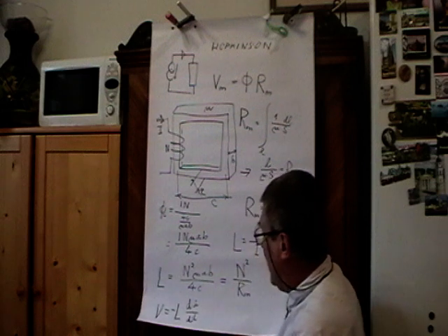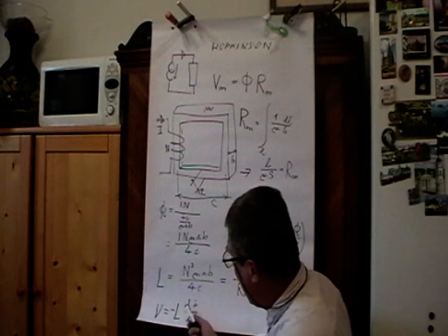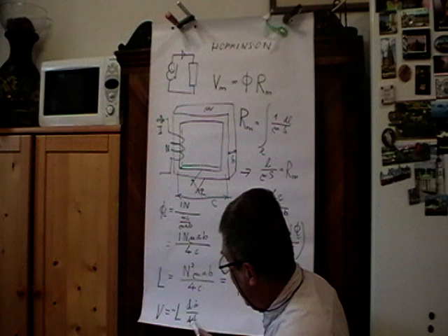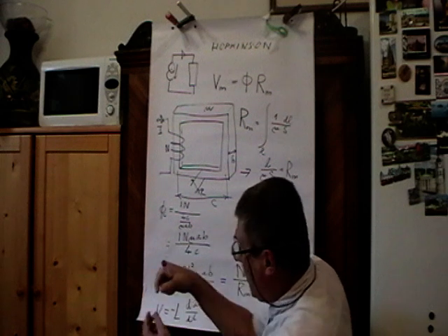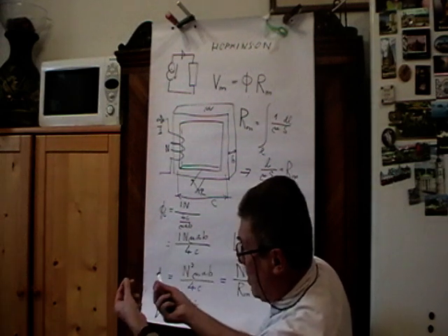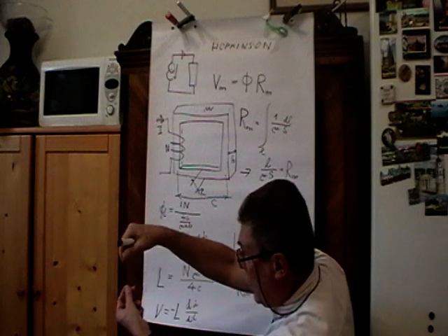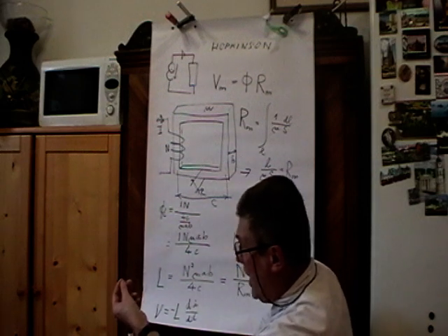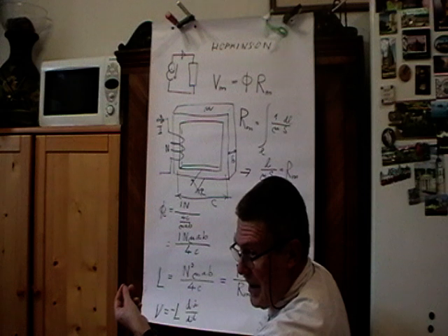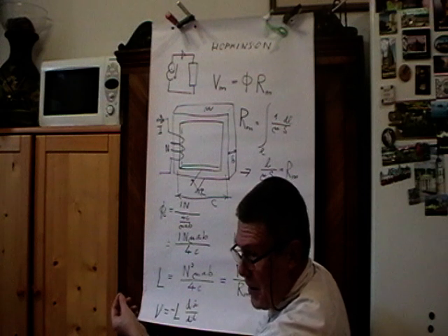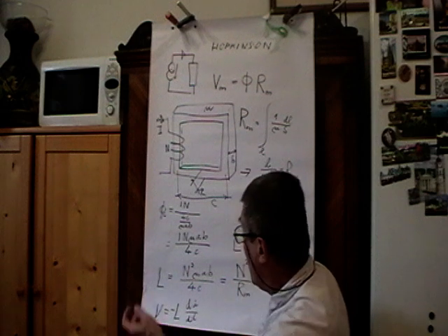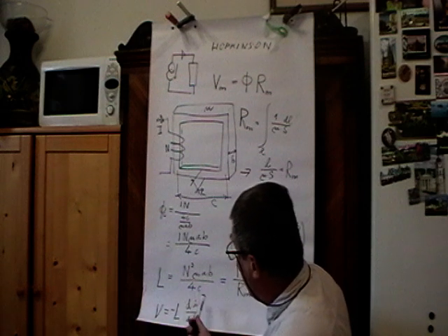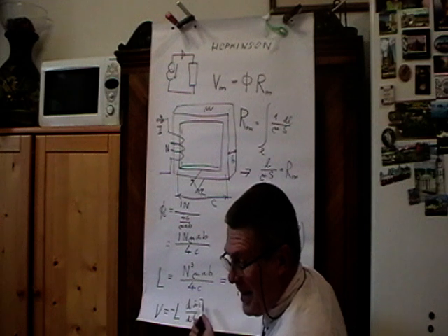So it depends on the time derivative of the current. But now, if you have 1 turn, there is some induced voltage. If you add 1 more turn with the same flux in the core, you have double the voltage. If you add n turns, you have n times the voltage that was in an individual turn. So this is why we have to count it so many times.